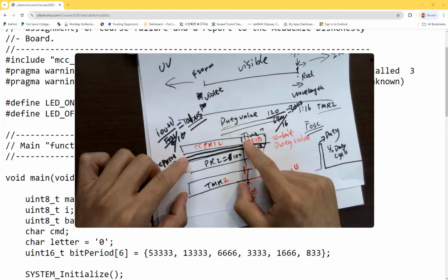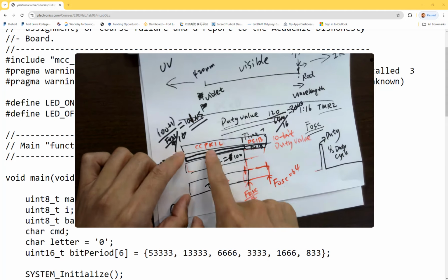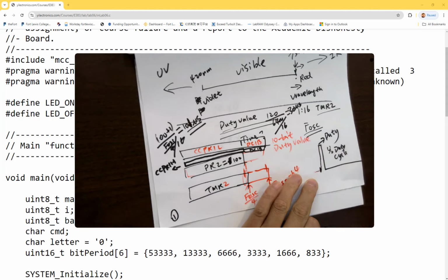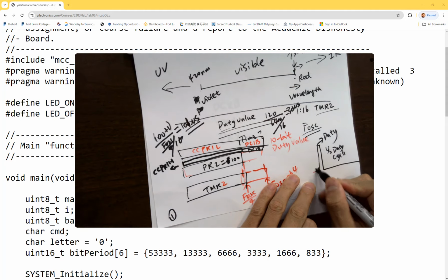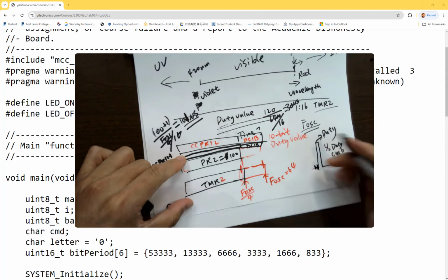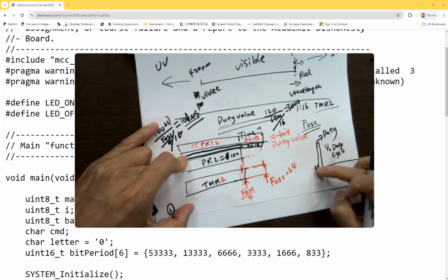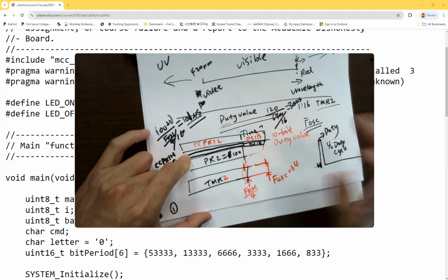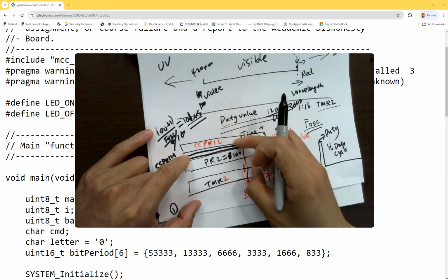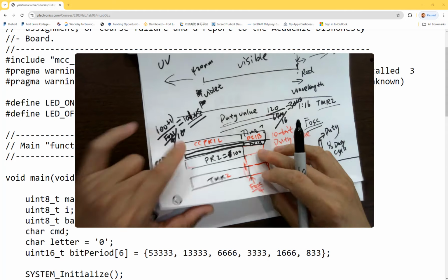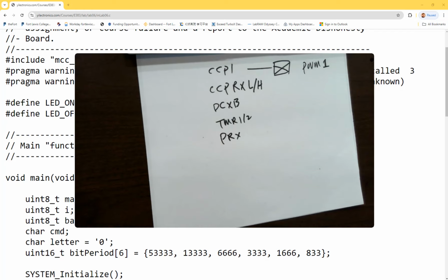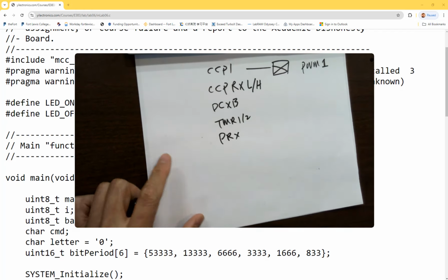This guy's not changing. Why? Because that 1 more cycle will be added to here. So it's extending that time by 1 more cycle, by 1/4 of a microsecond. After this is latched, it'll clear the timer and start counting for this time. That's something else, we don't have to worry about that. That answers your question, okay? Why? I don't know. It probably just needs 1 more cycle to keep it secure, so it's not being interfered with by other flip-flops. That's less important though, okay? So the high is just there.